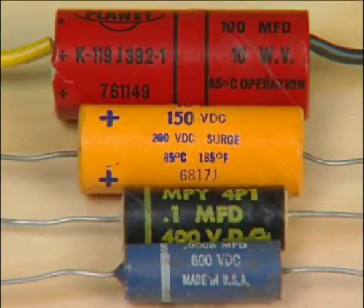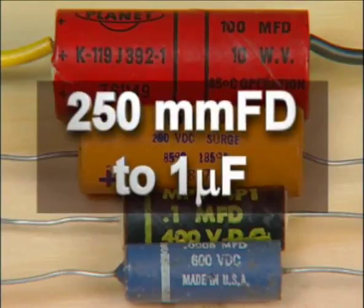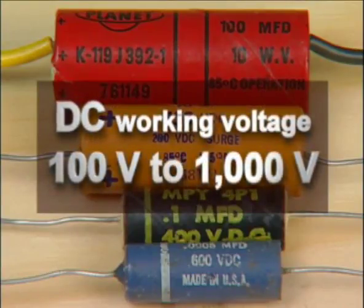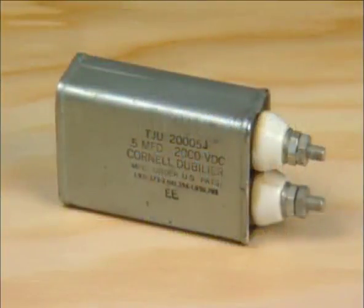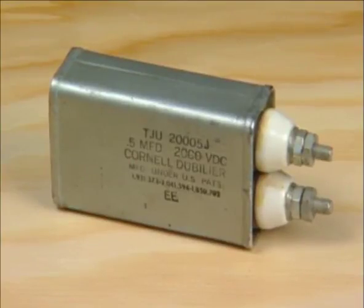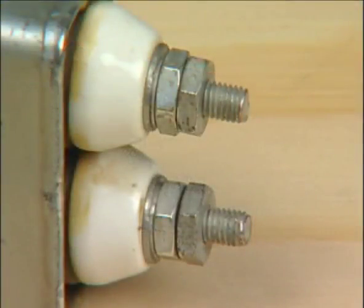Paper capacitors range in value from 250 picofarads to 1 microfarad with a DC working voltage range between 100 to 1000 volts. Paper capacitors used for high voltage circuits are impregnated with oil and then sealed in oil-filled metal containers. This capacitor has threaded studs with nuts for terminals.